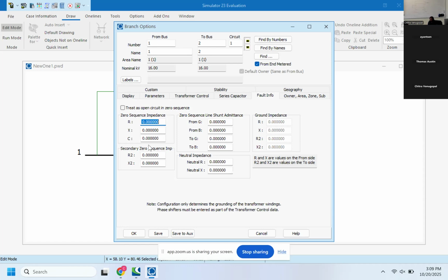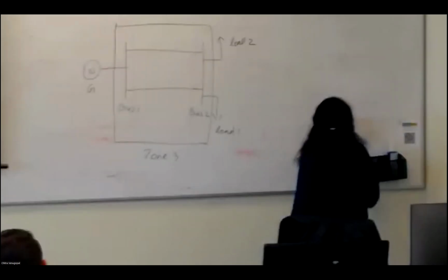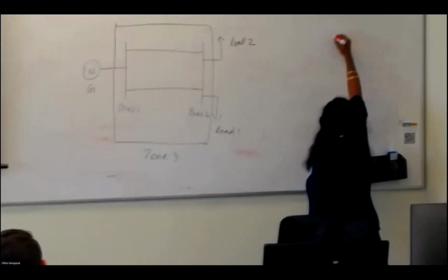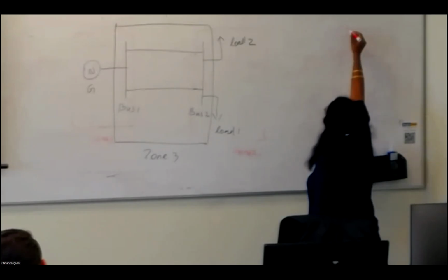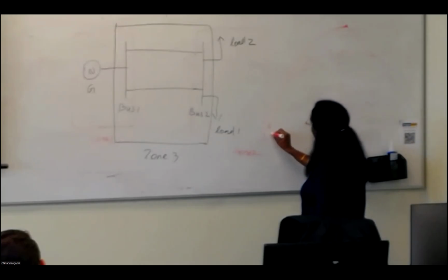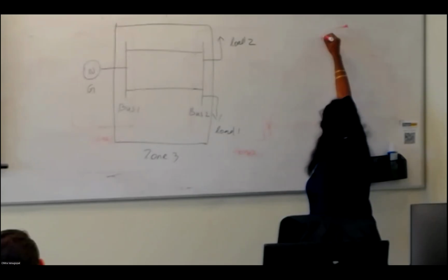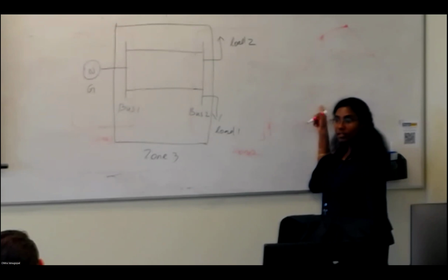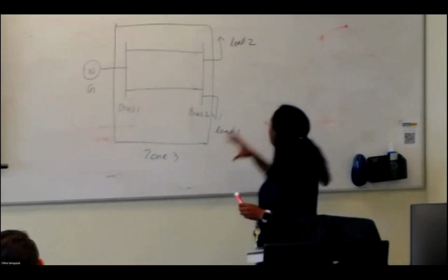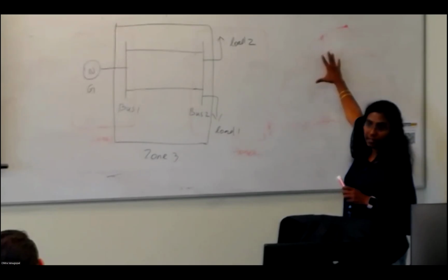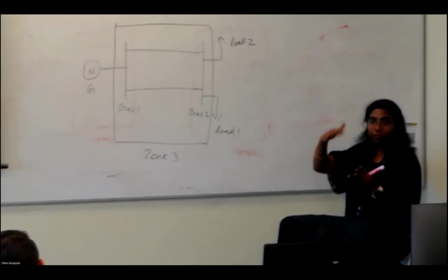RC and the capacitance. Why are we talking about the capacitance here? Because if you are laying out the transmission lines, if this is the tower, then the ground lines will be flowing from the top wire to the tower, ground. Okay. So there will be a capacitance between the ground and the top wire. So this is C. This C is what they are asking about. That is based on how tall the tower is. If it's a distribution line, then the tower will be shorter.